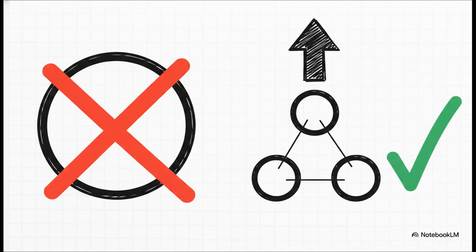The elegant solution is to bundle the conductors. Instead of hanging one massive solid wire per phase, utilities will run a bundle of 2, 3, or 4 subconductors spaced just a few inches apart. By spreading the current out across this bundle, you drastically increase the effective GMR. And if we go back to our math, a higher GMR simultaneously lowers the series inductance and raises the shunt capacitance. This powerful combination pushes the surge impedance loading limit significantly higher. It's exactly why you'll almost always see bundled wires on high-capacity 400 and 500 kilovolt lines.